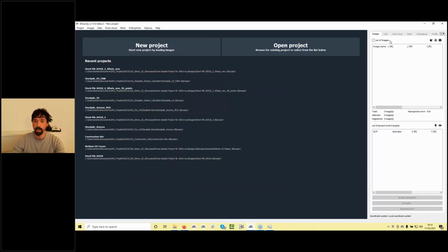What we do is a bit of a trick with the presentation. If you have a big point cloud, let's say 200 million points, we just visualize 50 million points to work more efficiently doing the rotation, visualization, everything like that. With 50 million points on your screen, you see more than you actually need. But if you calculate surfaces or anything like that, all points are taken in the calculations, so all 200 million.